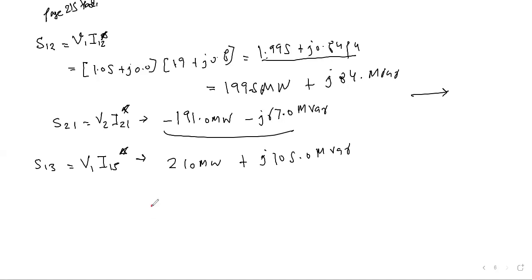The final step would be, like, this is the generator, right? So what is the load entering? Entering, because it was positive, the first value was 409.5, and 189 was entering. This is the real power, the P part, and this is the Q part. And then finally you see what is happening. This part is leaving the bus. Which part? The minus part.